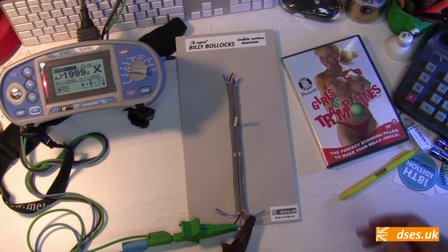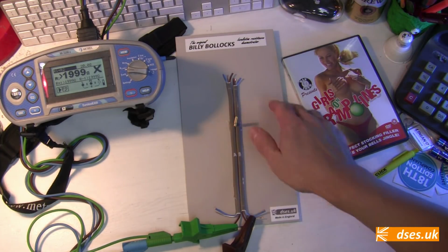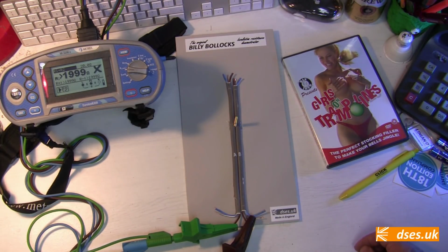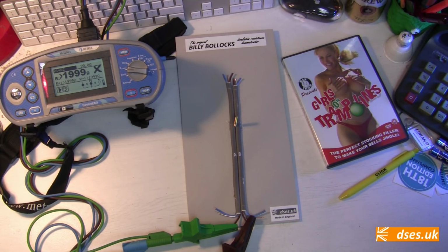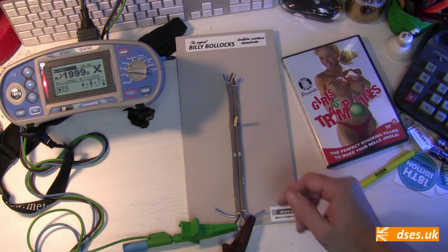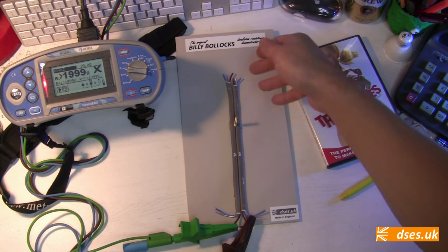That is to say, the screw is not in direct contact with the copper cores of these cables, and there's no resistive path between them via the screw itself. The screw has damaged the insulation though. It's eaten through the outer grey sheath and into the brown PVC protecting the line cores. Now, although there's no path through this screw when dead, let's see what happens when we start pushing an electromotive force into these cables, which is what would happen if I were to switch these circuits on.